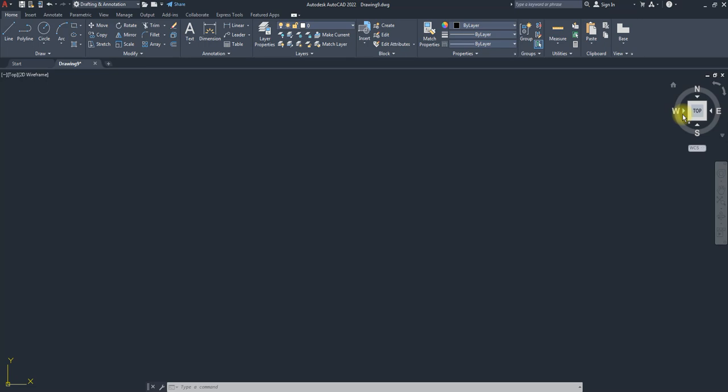This origin that we are starting from is called the world coordinate system. Right? So for every graph, when you start drawing your graph, the first graph that I draw is the world coordinate system. In the case of AutoCAD, it has its own first graph, the origin, which is the world coordinate system. By the time you start shifting this origin from where it is to a different location, it changes from being the world coordinate system to what we call the user coordinate system, because you have modified the world coordinate system.